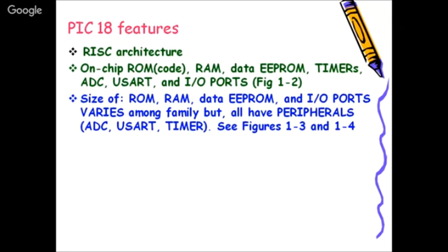So they have divided it in terms of banks. The 4 kilobytes is divided so that each bank is of 256 bytes in case of PIC. So they have almost 16 banks, 256 bytes per bank, so 16 banks of RAM for 4 kilobytes. So you can address them or use them. And then there are special bits, 3 bits to have addressability, which bank to access. When we see the RAM memory structure, you can see how it is there.